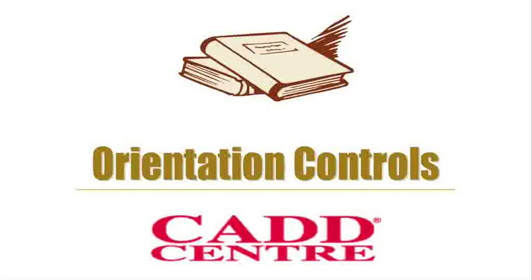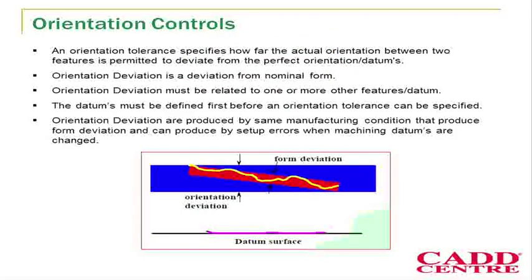Next we discuss orientation controls. There are three types of orientation controls. We call them perpendicularity, angularity and parallelism. The orientation tolerance specifies how far the actual orientation between the two features is permitted to deviate from the perfect orientation of the datum, or you can say it is a deviation from the nominal form.